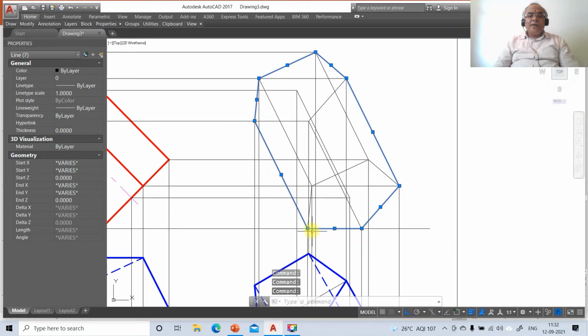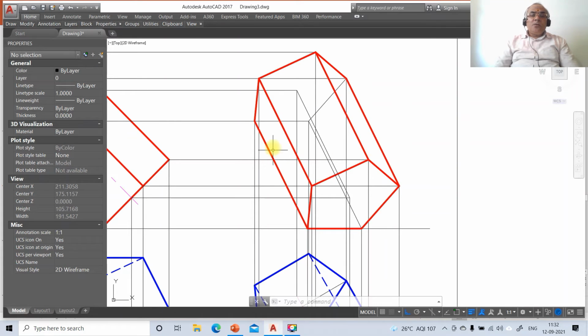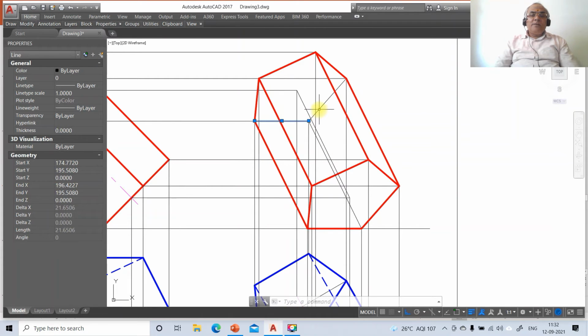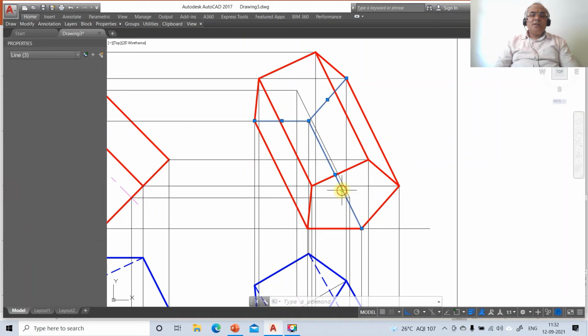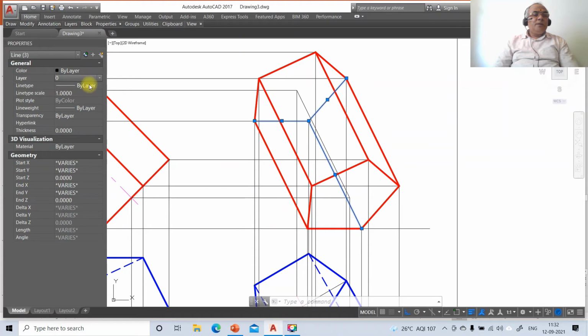and then the surface nearer to the observer is visible, and this edge will become visible. Go to layer, make that as front view. Now two visible edges can never cross, so obviously these edges are going to become front view hidden, and this distance is 20. So now the left out portion is only this.